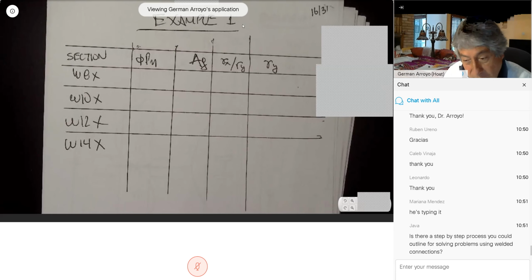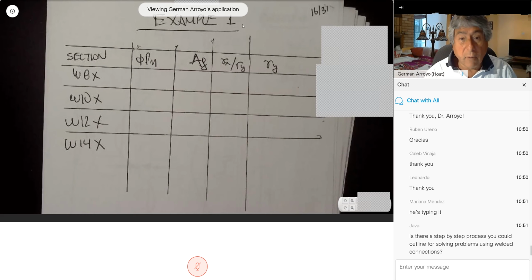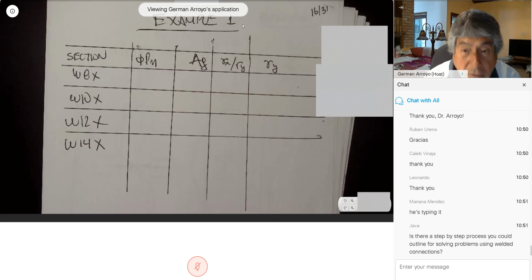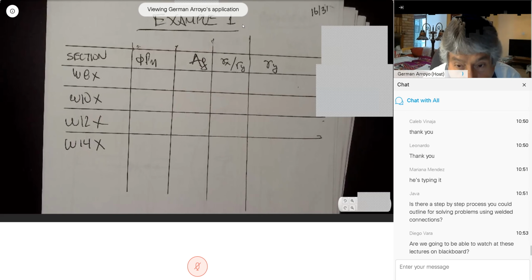And also remember now it could be tension, it could be eccentric shear. Now we have compression. So you have to understand what type of problem they're asking. Sometimes I give a problem where the connection is not eccentric, and the way you look at the connection it appears to be eccentric. So you go and solve a problem that is completely different and impose your problem. So you have to observe what kind of question is in front of you: compression, tension, eccentric shear.